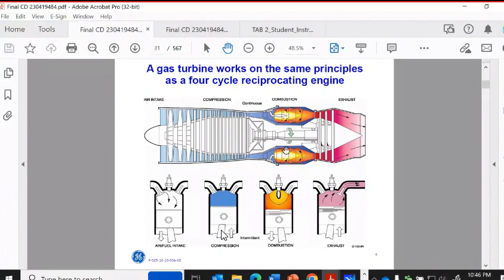We'll cool it with the CDP air, keeping the flame centralized, with low impact on the high pressure turbine nozzle. Everything remains good. And like I said, this is when I talk about high efficiencies on heavy duty turbines or aircraft engine turbines. It's because we have the ability to do all 4 cycles in one simple rotation.